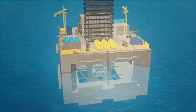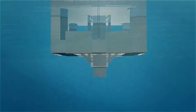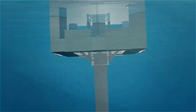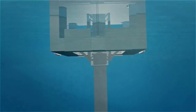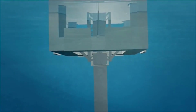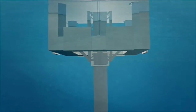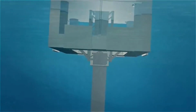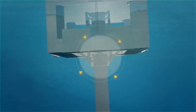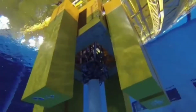During fabrication, the cold water pipe is almost rigidly connected to the platform. As the fabricated length becomes longer, the pipe's response to waves and currents increases and begins to affect the platform. Because there is no way to accommodate its motions relative to the platform, the coupled structure is particularly vulnerable to storms, with the largest loads and forces concentrated at the lower location.